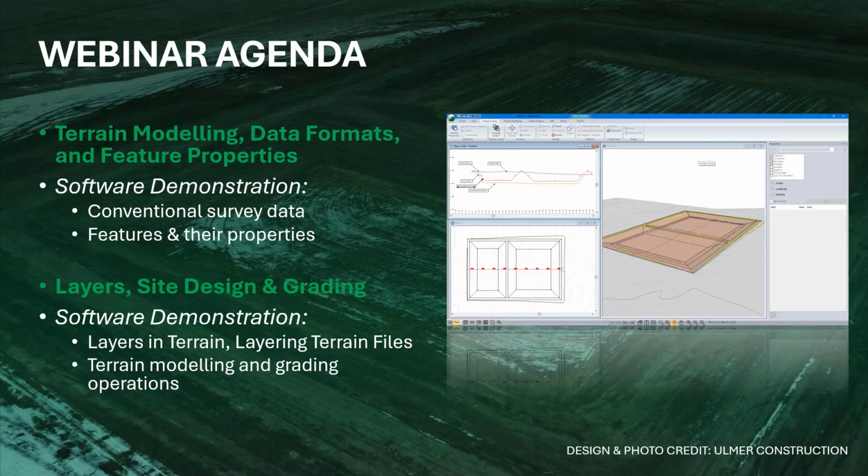The second half is going to be diving a little bit deeper into more of that site design and grading side of terrain. Here we're going to be discussing layers, both layers inside of a terrain file, as well as how you can layer terrain files in order to create different site design and grading projects. We're going to be taking a look at that, and a great example shown actually from one of our clients here on the screen from Almer Construction. We're going to be looking at a similar pond example for site design and grading.